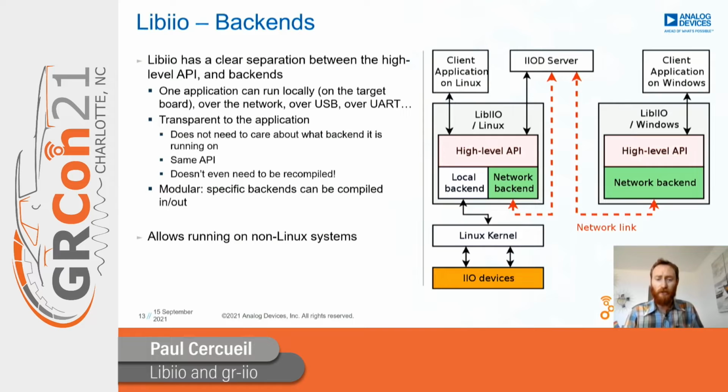And the good thing with these backends is they allow LibIIO to be used on non-Linux systems. So you can use LibIIO remotely using the network backend or the USB backend on a Windows PC, for instance. And that's what makes it able to run on other operating systems.